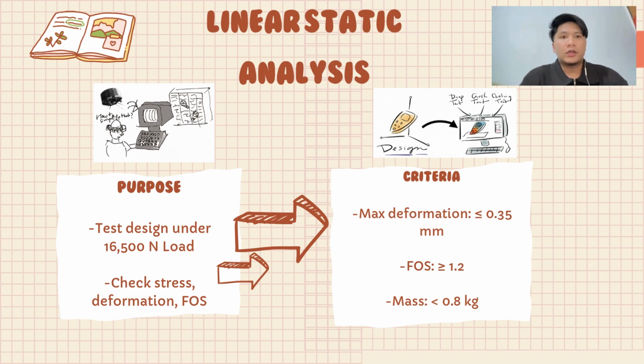I am student 1, adik FARHAN bin Muhammad ROSLAN, and I will perform the linear static analysis. The purpose of this analysis is to test the design under 16,500 Newton of load, which we apply to the 3 designs that we created. Secondly, we need to check the maximum stress, which is the equivalent von Mises stress, the total deformation, and finally the factor of safety, which is FOS. The criteria we need to achieve are maximum deformation below or equal to 0.35 mm, FOS between 1.2 and 3.0, and mass below 0.8 kg.